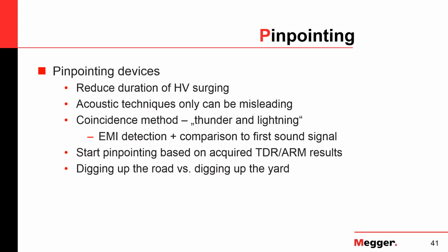Now, pinpointing devices. Why are we doing that? Technically, you could just thump with a high energy, and you can thump for hours or days, and you can just walk along the cable until somebody picks up the noise somehow. Well, this is not a preferred way of doing that, because these thumps are done typically at a fairly high voltage. So the longer you stress the cable, you risk of getting into something. So the pinpointing device actually reduces the time that you need to be surging.